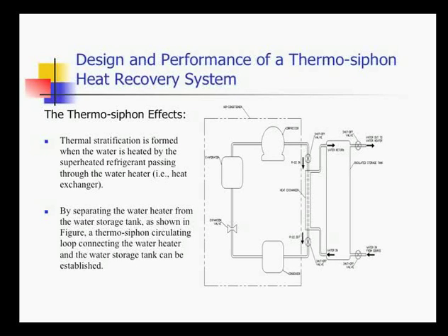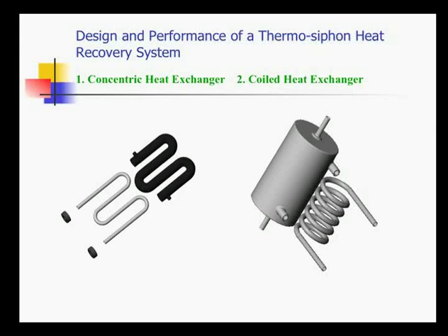Thermosyphon effect is formed when the water is heated by the superheated refrigerant passing through the water heater, as I explained earlier. And by separating the water heater from the water storage tank, a thermosyphon circular loop connecting the water heater and the water storage tank can be established. These are the two examples of the water heater or the heat exchanger that we developed and designed.